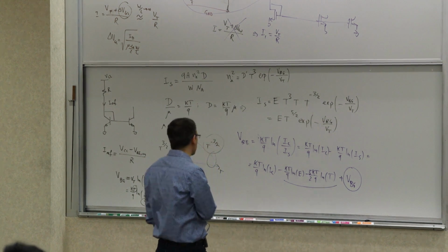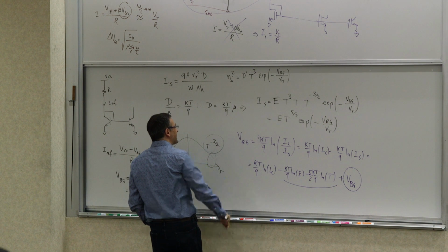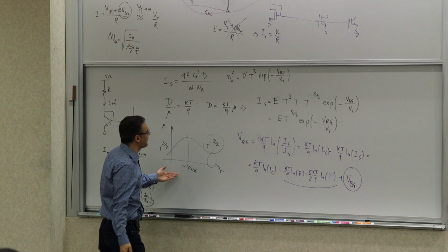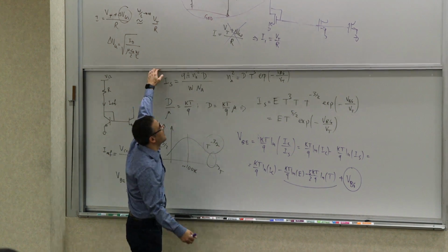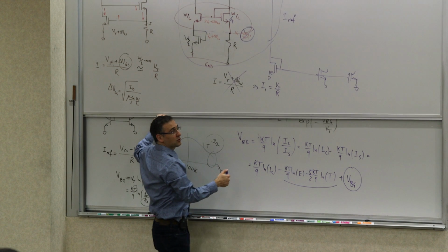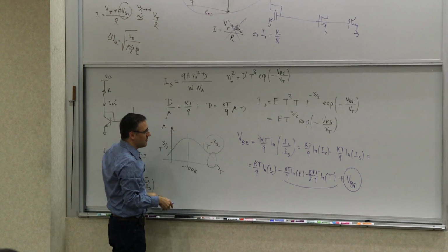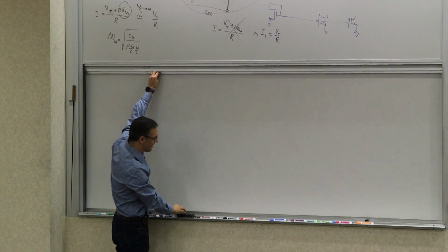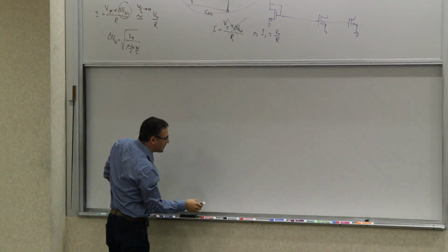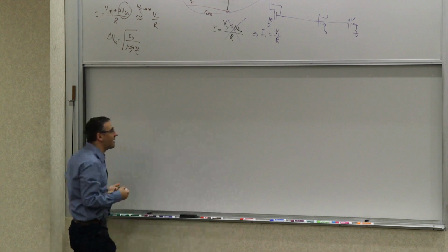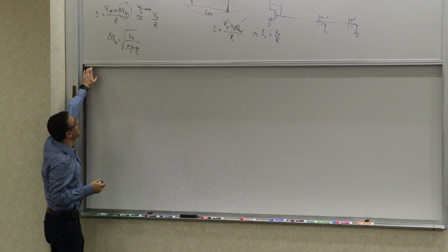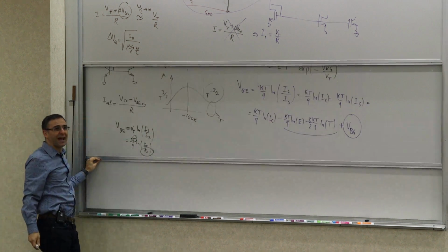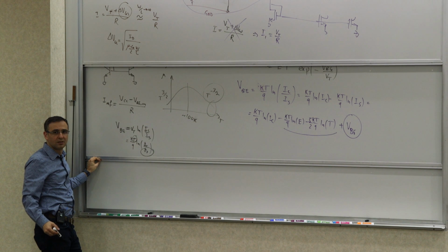So the question is, how do we get there? The first thing we see is that it's a negative temperature coefficient, right? So it's still bad, because it's a negative temperature coefficient divided by a positive temperature coefficient here. So it still gives you a negative temperature coefficient. It's less process dependent, fine, but we still need to work on that. So how do we do that? When you look at that expression, for example VBE, is there something in there that actually has a positive temperature coefficient?